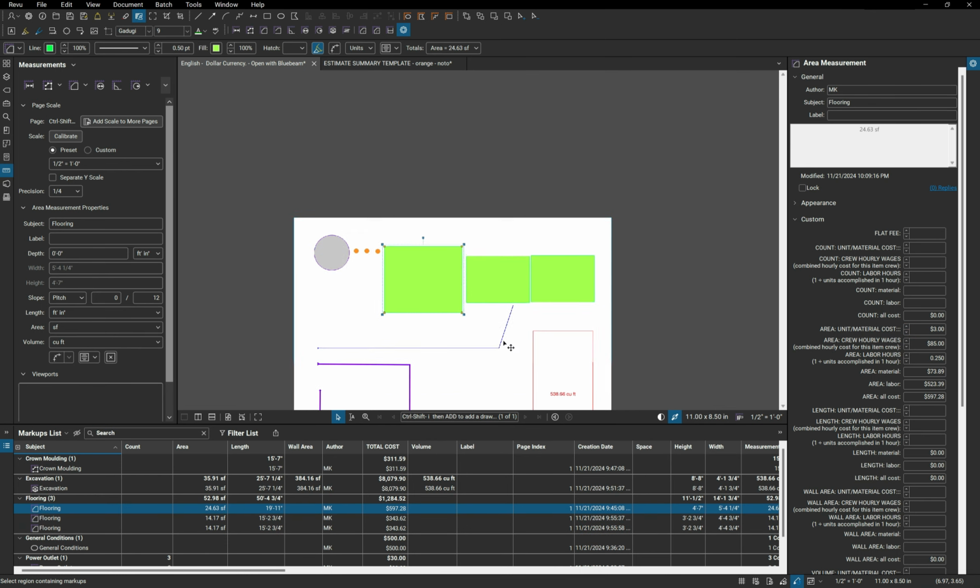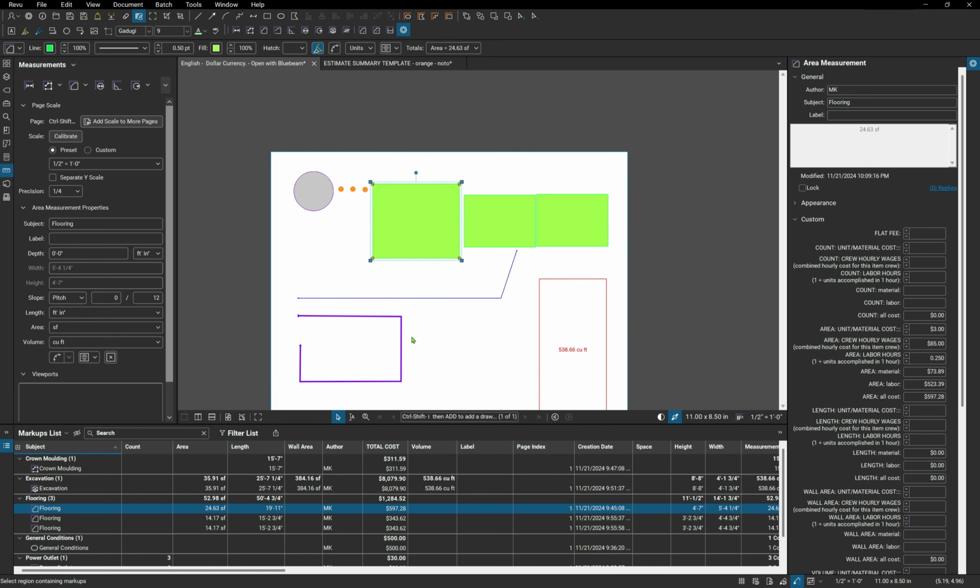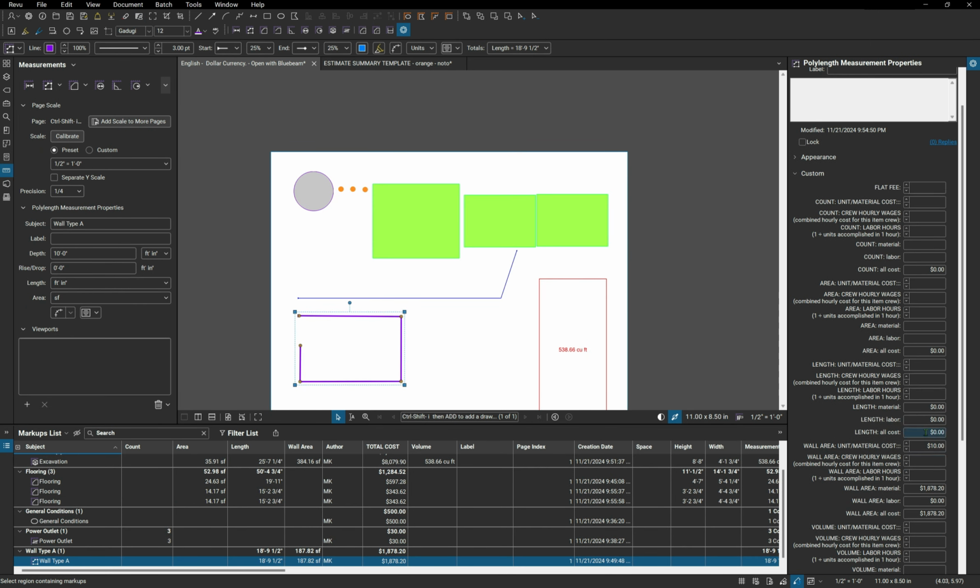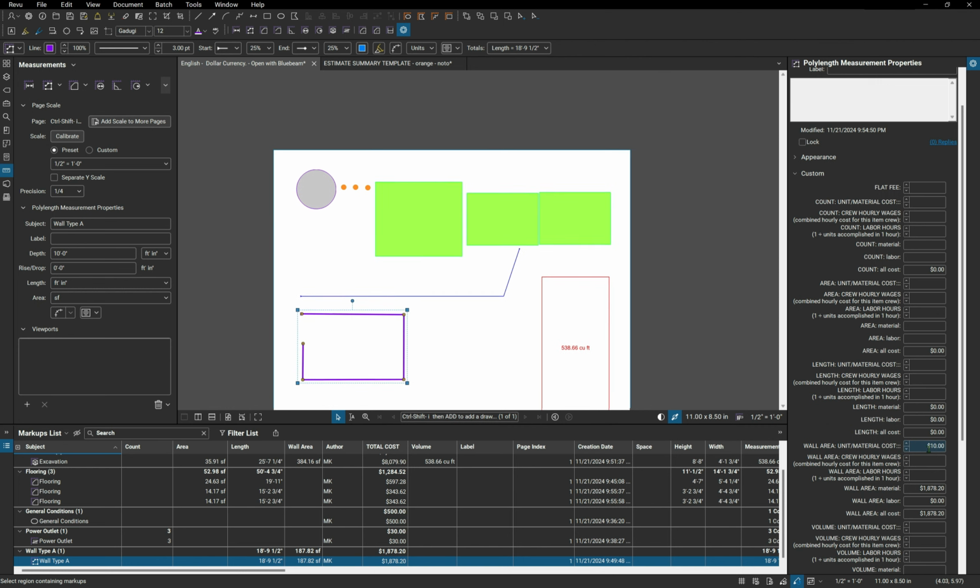And you can do it all with any other measurement. So let's say you have a wall that we were originally charging a flat $10 per square foot of the wall area. So instead now let's say the material costs us $2, but we have 2 employees, a crew of 2, and this crew is also $85 altogether. But let's say this crew can produce 7 square feet of this wall area in 1 hour.